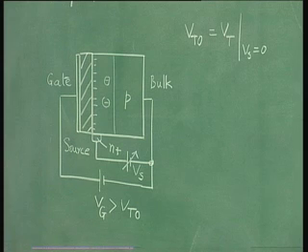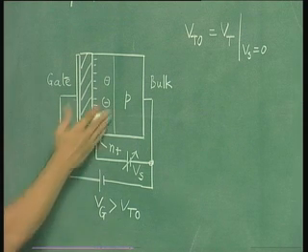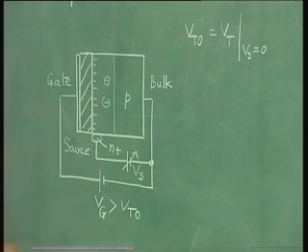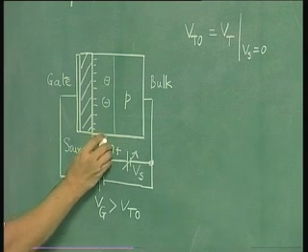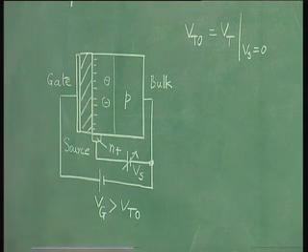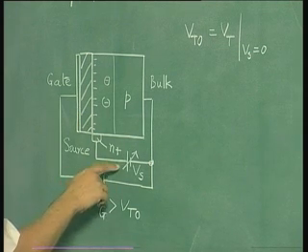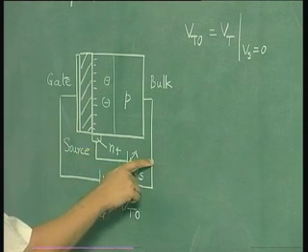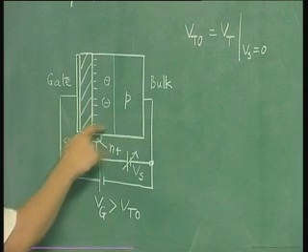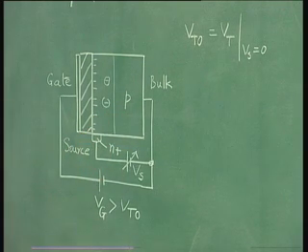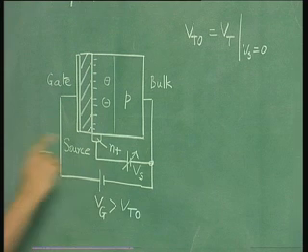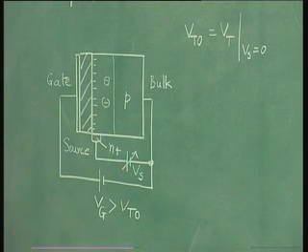So if you apply a forward bias here, there are two problems. One is that there is a large forward current in the device which you cannot control by the gate, and also you cannot have a very wide variation in the voltage to control the N plus region, to control the inversion layer charge. Therefore we are only allowed a positive voltage to the N plus contact with respect to P. In other words, the P N plus junction should only be reverse biased. Okay, now we start increasing Vs. What is the effect?